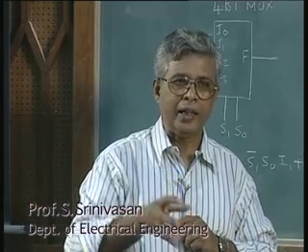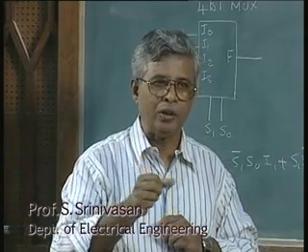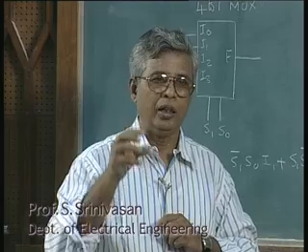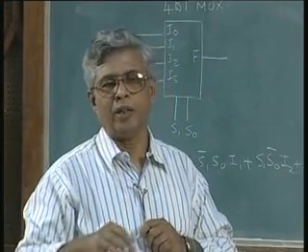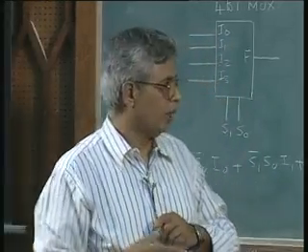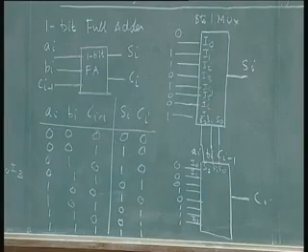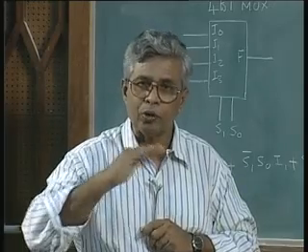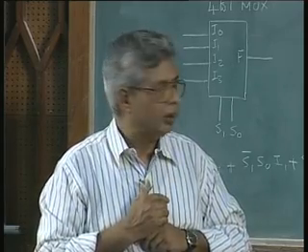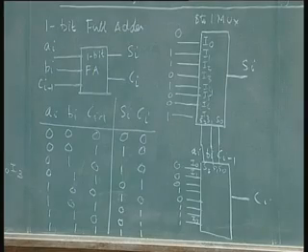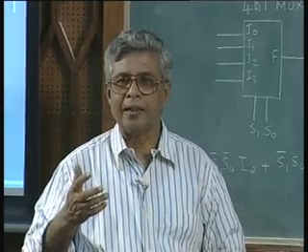In an integrated circuit design, the essence is to fit into the available or the given hardware as much functional complexity as possible. So, we can optimize it, of course. I am going to show you, this is a waste of 2 8 to 1 multiplexers. This is the approach I want to show you, but this may not be the best way to do it. Can I optimize it? Instead of using 2 8 to 1 multiplexers, which I would say is an overkill for this simple problem, can I do it in a slightly simpler way?